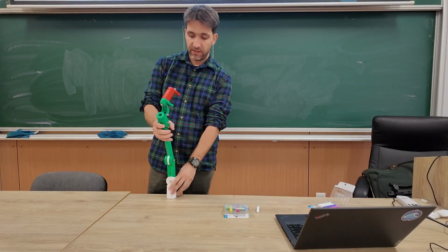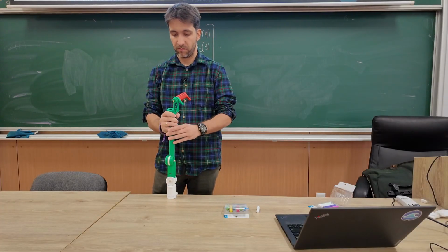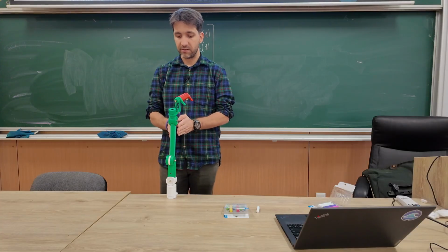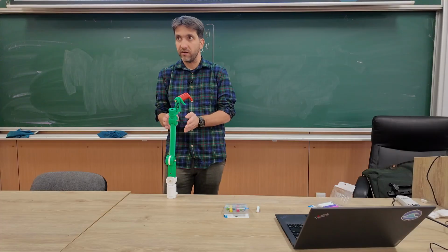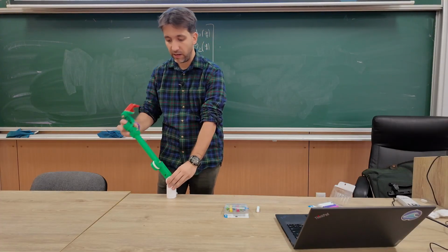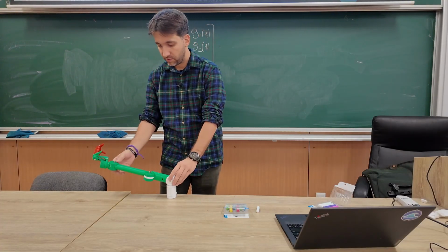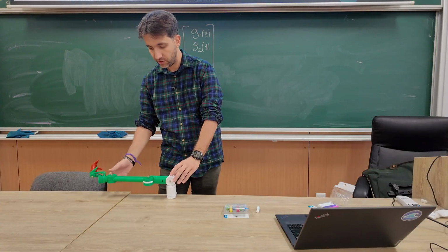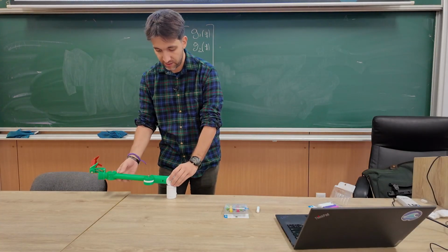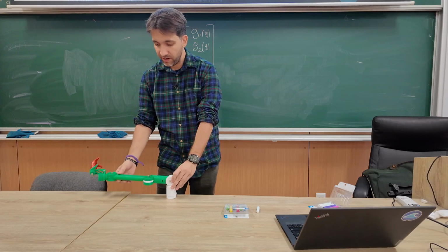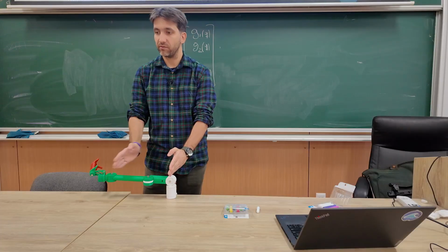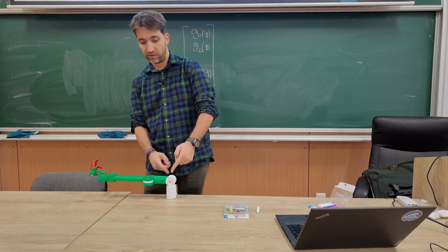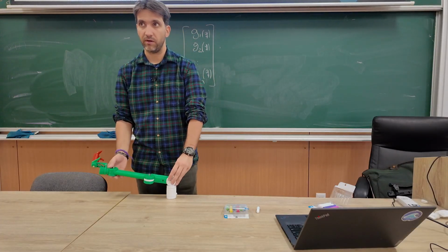If this robot is like this, standing up, basically for all the masses the distance from the axis of rotation is very small, so the torque they generate is very small. But here I have the same masses, but over a bigger distance from the axis of rotation, so they generate more torque that this joint has to overcome, right?